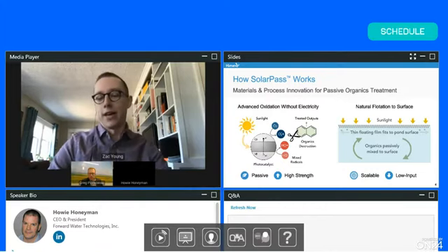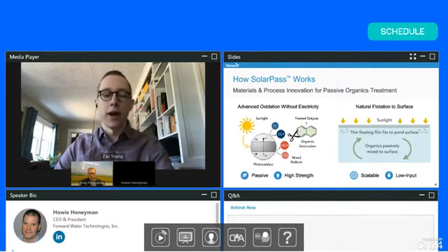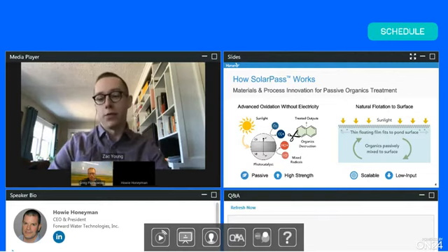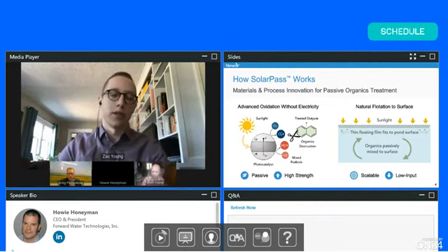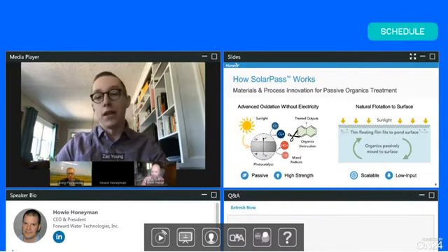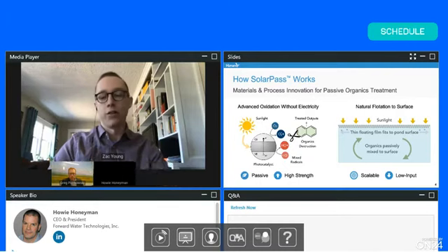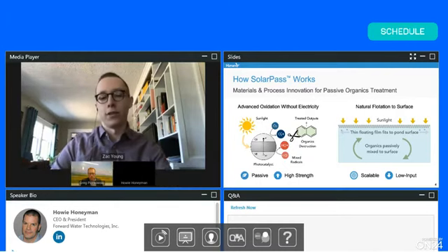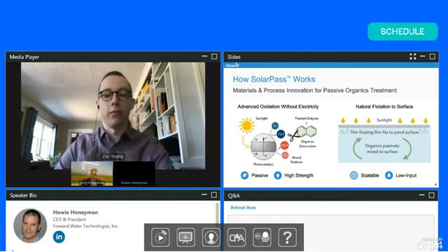The premise is that at the surface of the water, where sunlight intensity is strongest, we can facilitate that reaction, mix the particles through to interact with the contaminants, and then at the end of the process, recover them either for reuse or ultimate turn down of the treatment system, making sure that we're leaving nothing behind. There's no waste generated. The process adds our materials, operates with exposure to sunlight, and then recovers them at the end of the process.